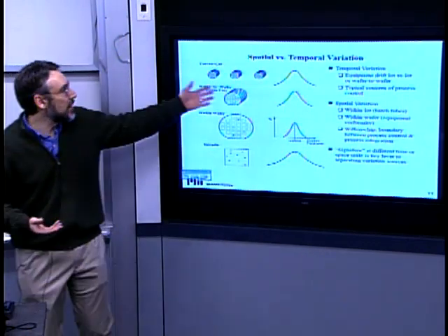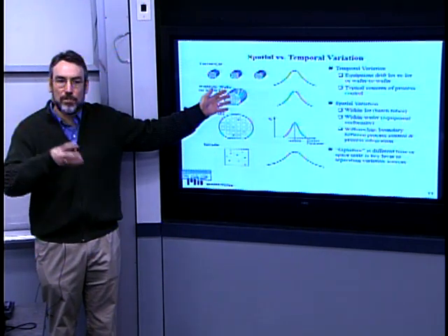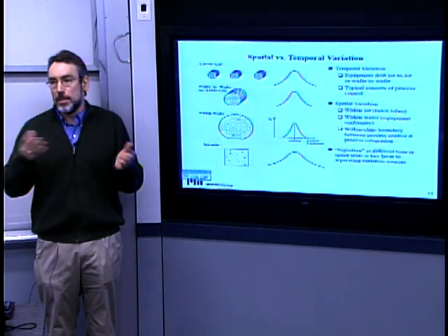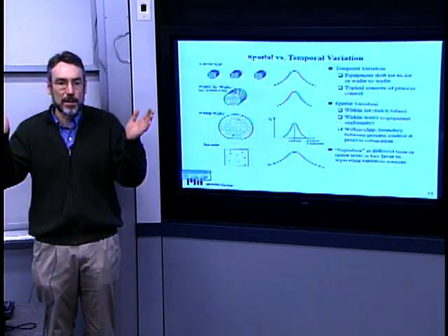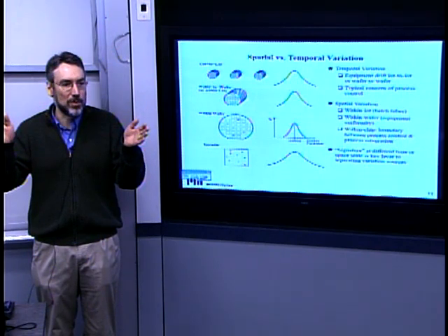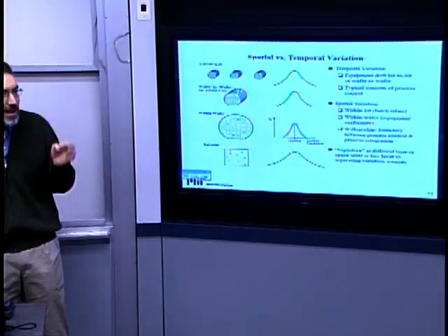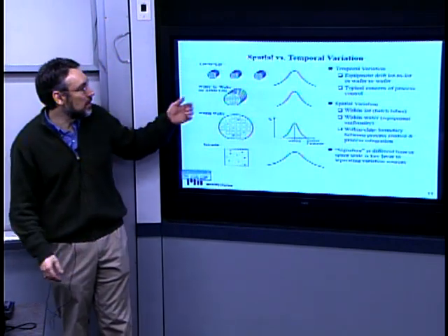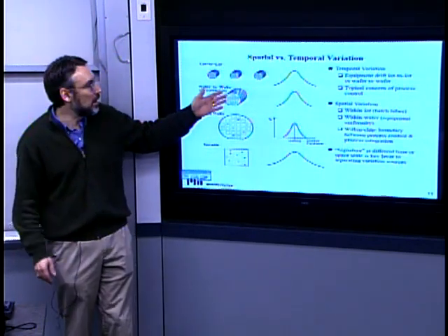And that might arise because of changes in the equipment state from one run to the next, right? The first wafer may have a pristine equipment with no buildup of material on the chamber wall. The next wafer might see a slightly different process, unintentionally, than the previous one because of changes or degradation in the equipment state over time affecting that wafer state. That might be an example.